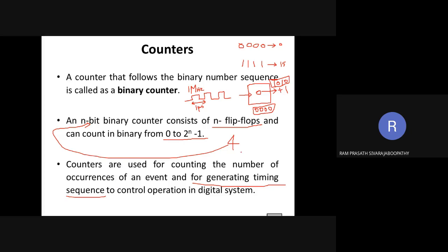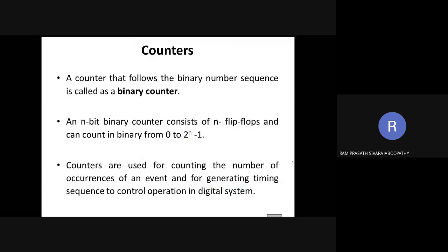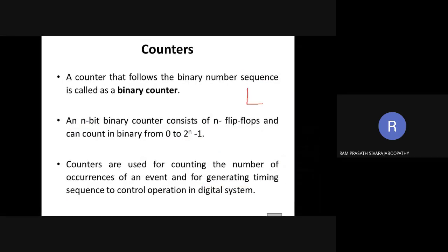Okay, now when we say counter, how should it work? The same counter I am going to use. So it's a 4-bit counter. Initially we assume it has the value 0000. Now what I am going to do is place a sensor. If somebody crosses this path, at that time it will generate 1. So what will happen if a first person enters?